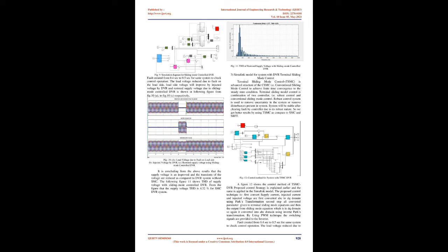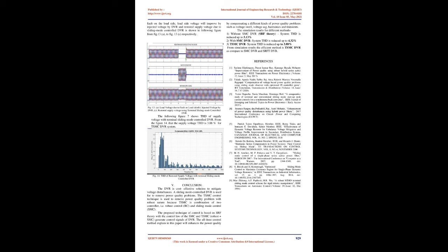Conclusion. The DVR is a cost-effective solution to mitigate voltage disturbances. A sliding mode controlled DVR is used to remove power quality problems. The TSMC control technique is used to remove power quality problems with robust nature because TSMC is a combination of two controllers, i.e. robust control, RC, and sliding mode control, SMC. The proposed control technique is based on SRF theory with the control law of the SMC and TSMC, robust control and SMC, to generate control signals of DVR.